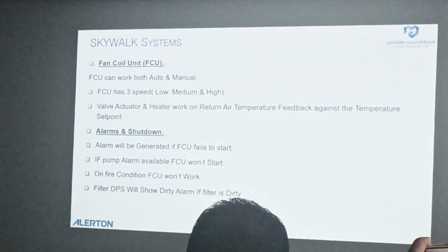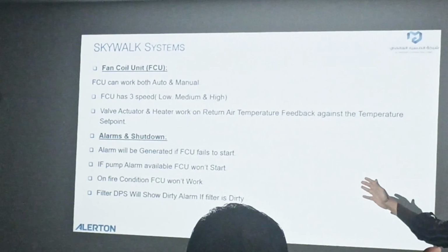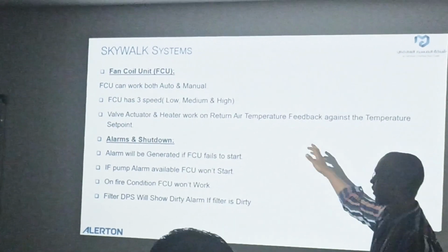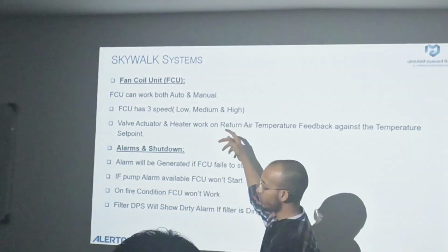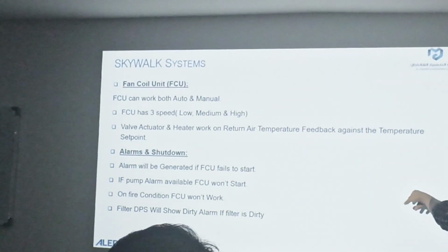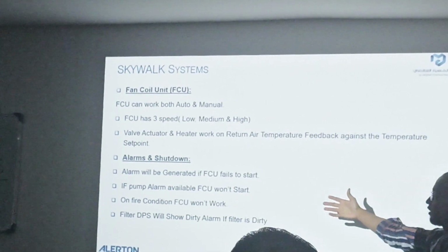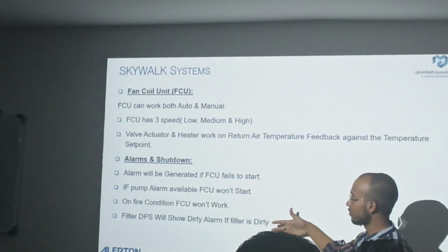Now, just now I told you the sequence of the FCU. These are the sequence. It will work both in auto and manual. It has 3 speeds, and the valve actuator and heater work on return temperature. And these are the alarms and shutdowns for the FCUs.